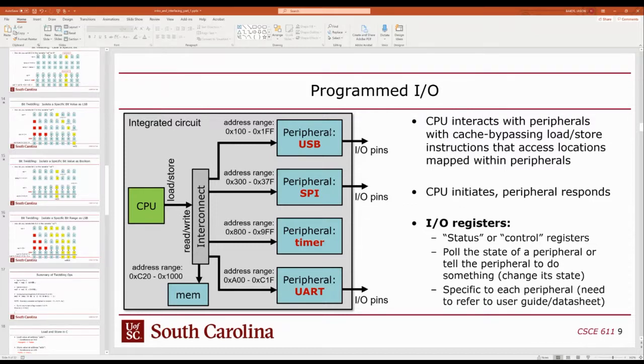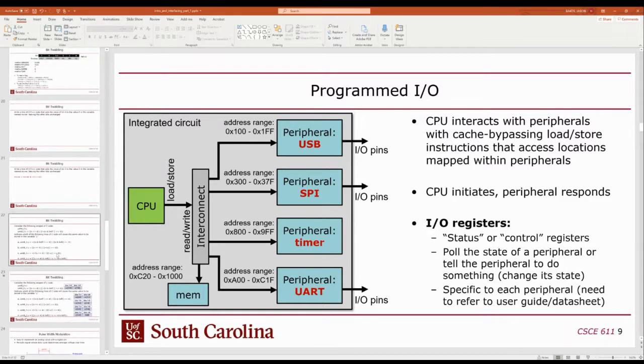Now you might say, wait a second, Wi-Fi on a chip? I thought you said that analog and digital don't mix. No, they don't. But the fabrication technology of a cell phone chip is very carefully designed to provide isolation and to achieve very good mixed signal performance. Back when I used to design chips like that, in grad school, we had this fab called silicon on sapphire, where the substrate of the chip was made out of sapphire, which is a really good insulator, and then they would grow the semiconductor material on top of that.